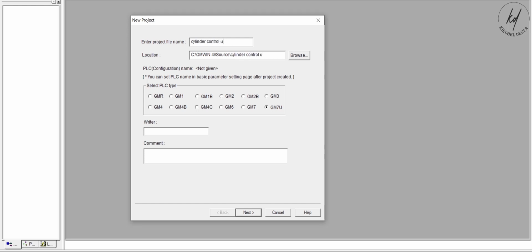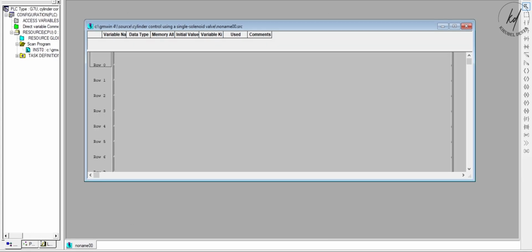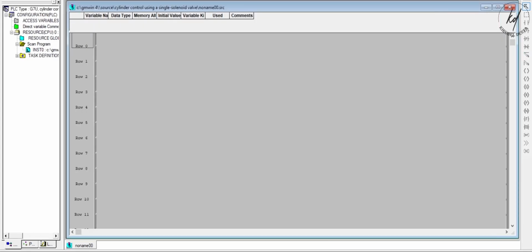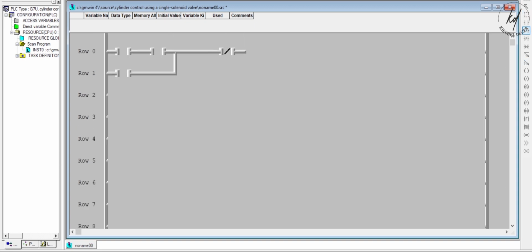By modifying the ladder diagram of the above, here the up counter is used and executes the task, that is, as the push button is pressed the supply cylinder advances and returns 3 times. After all, the supply cylinder stays in the retracted position as long as the push button is not pressed again. It is similar to that of the previous one with the replacement of the on timer by the up counter.